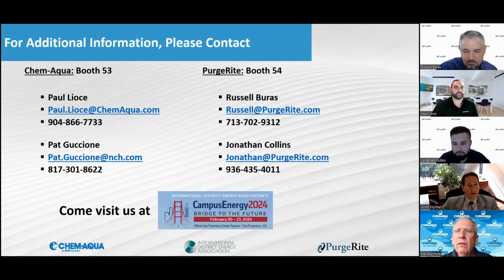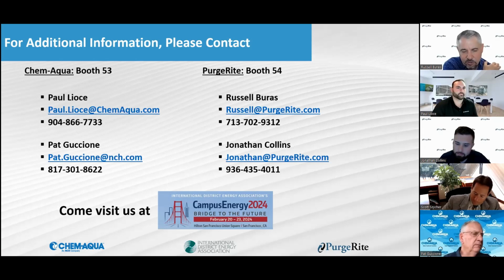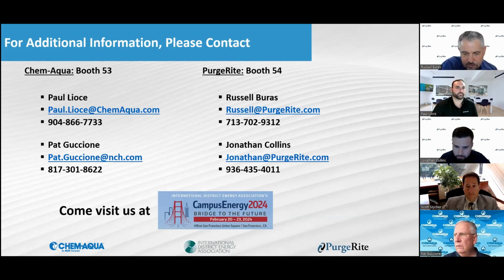Question came up on directions. Do you flush the system in the intended direction of the system's design flow, or do you backflush in the opposite direction? We flush in the direction that it's flowed. On chilled water and heating water systems, we don't reverse the flow. On geothermal systems, you do reverse the flow. It's typical standard practice that you will flow both directions when flushing a geothermal system, but on the chilled and heating water, it's the way that it's designed.